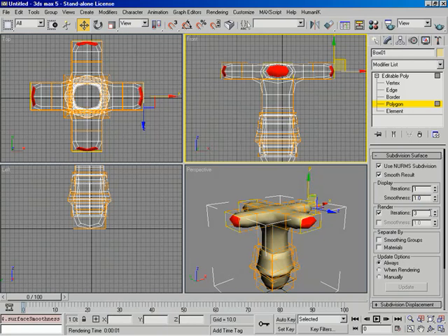Let's go ahead and come down here to separate by. We have two different ways basically to allow the NURMS subdivision to determine when additional geometry is added in between two polygons that are connected together. By smoothing groups, what this will do is if two different polygons are in separate smoothing groups, then it will not add additional geometry in between them. It keeps them separated so we can keep a hard edge there. Right. And same thing goes for materials.